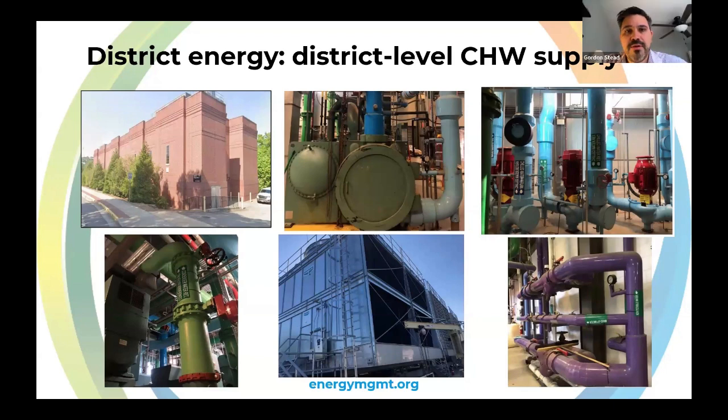If you have low delta T on one particular air handler on your connected load, that has an impact on the efficiency of the chillers upstream. Where we have 3 pipe systems creating excess flow and low delta T, that impacts your chillers. Trying to manage all of those together is a lot of the complexity, and we certainly have a push to convert 3 pipe systems to 2 pipe systems for that.